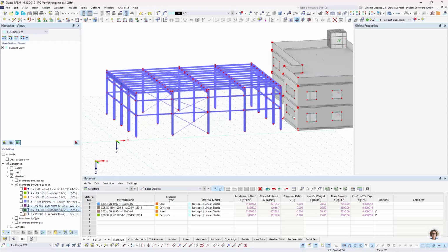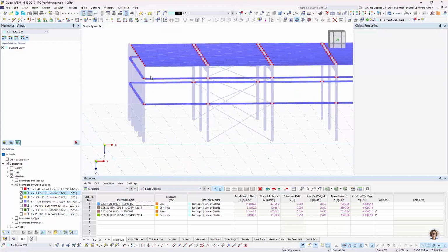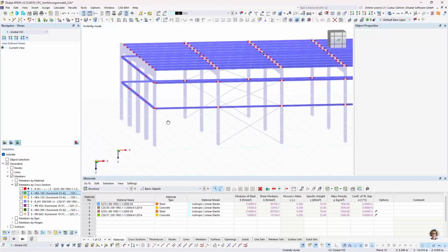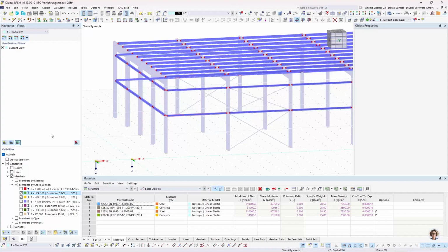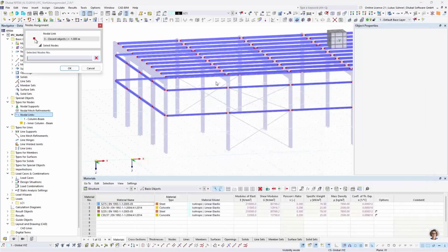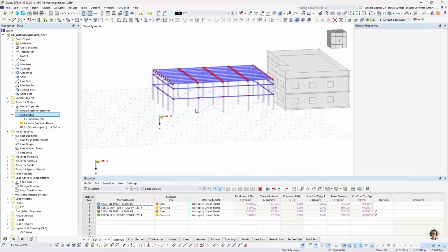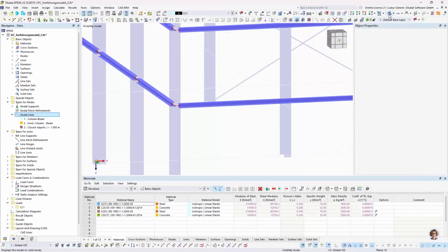So let's say we want to connect all the coupling members from my structure, which is between my frames usually. They should be connected to the columns and so on, and to the main beam. So another node link. I skip the renaming now. I think it's clear how it's working. So I select all of those nodes. And again, I say, please look for members close by. And maybe use a hinged connection.